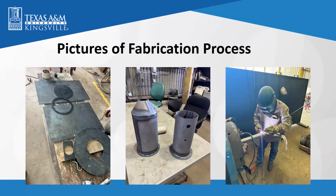I think we had some other questions. Go ahead. Was there any thought process behind the angle of approach the air has as it goes into the combustion chamber? Did you offset it so that it creates a vortex? Yes, that's actually a really good question. Another rule of thumb with these is you're supposed to have it above half of the plane sheet in order to create a vortex inside. And did you offset it from the center of the combustion chamber like this? Yeah. Okay.